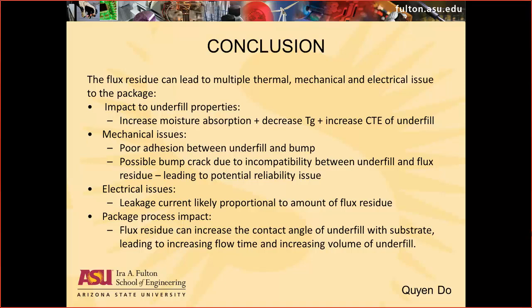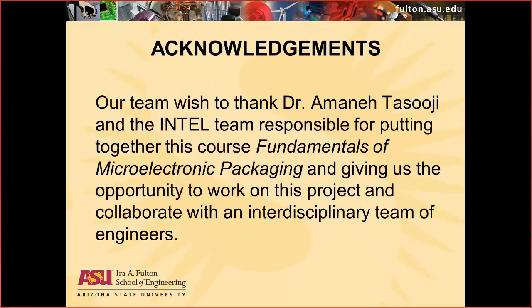Also, there were some papers and experiments that proved that the leakage current is likely proportional to the amount of flux residue accumulated on the substrate. And nevertheless, the flux residue can impact our package process because flux residue can increase the contact angle of underfill with substrate, leading to increased flow time, which can have a big impact in high volume manufacturing. So that's all our team has for the presentation.